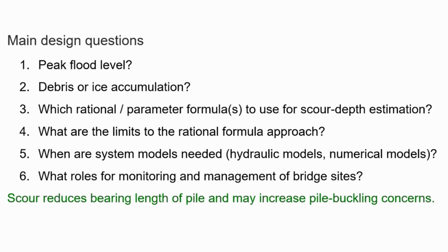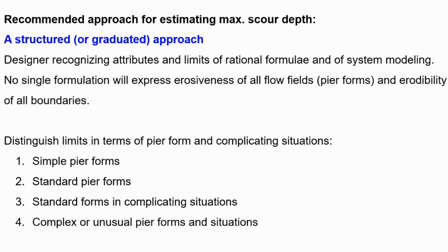So Iowa, for instance, has got 5 crews which inspect all the bridges every 3 years. And they increasingly use things like drones. Before they had to have trucks with articulated arms that can go under bridges and so forth. And they measure scour, and scour reduces the friction bearing length. We have a graduated approach in design, as indicated through here.